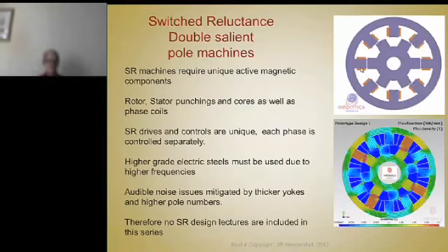Now the one below has 4 attracting points, 90 degrees apart. So instead of trying to make itself elliptical as it is commutated, it becomes more like a square. So just on the face of it, the one at the bottom is quieter.